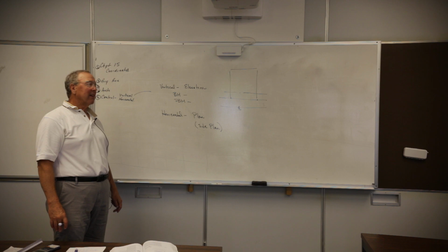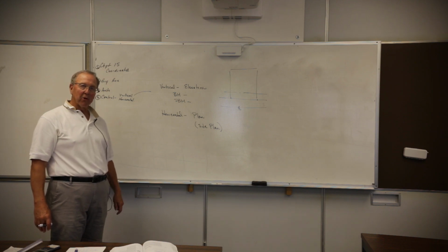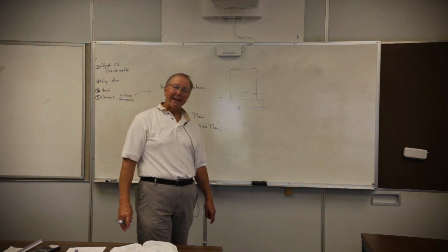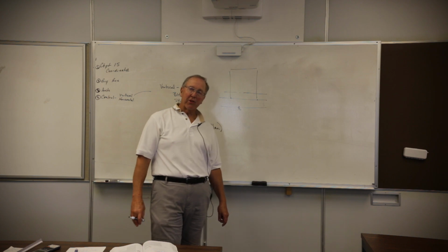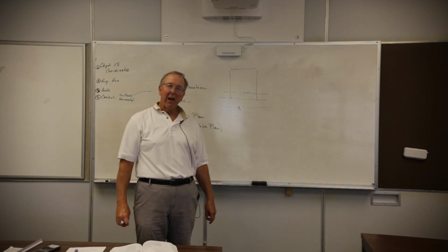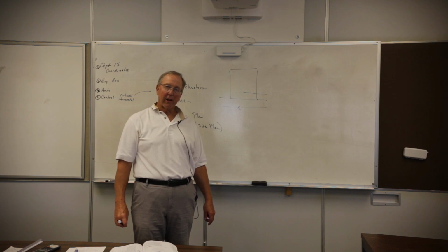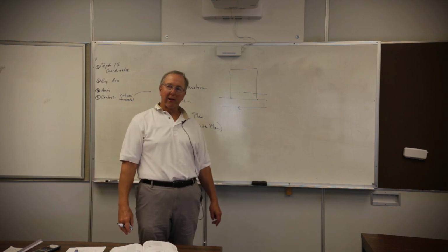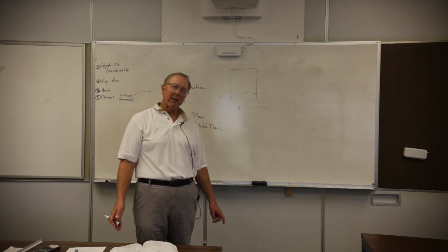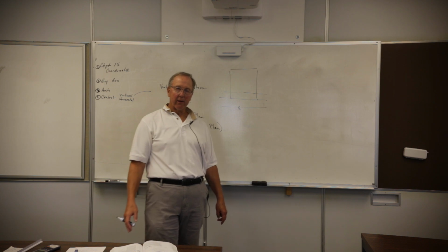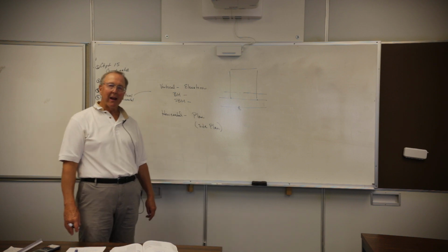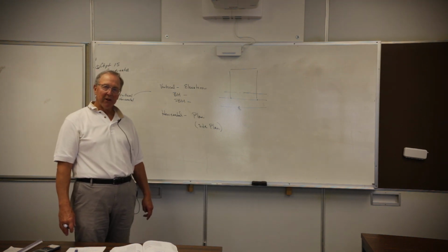Now, where you set this thing has got to be indexed to something that's non-destructible if possible. I've seen guys go out in the field and play with stakes. They knew they laid it out wrong. They went out in the night, moved the stakes to get it to conform with what it was supposed to be, and then they blamed the contractor because the contractor didn't follow what he was supposed to, and the building now encroached in an easement, was over the building line, and they were going to have to spend a lot of money to change the foundation to meet the local zoning criteria. So you want to make sure that when you lay something out, you've got it indexed to something that somebody can't tamper with. They can't go out there and move it or change it.